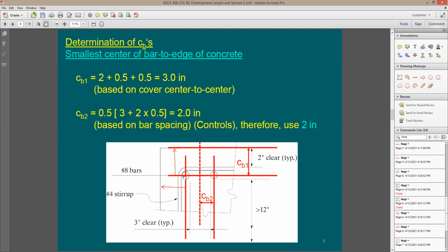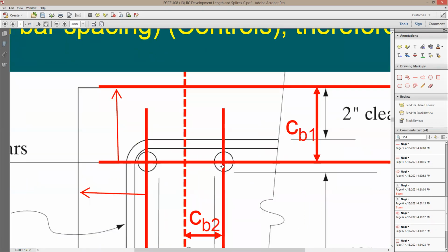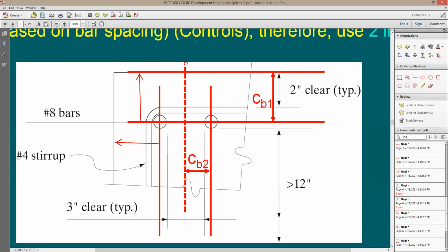So this works fine. I mean, it is easy to explain it when it comes to a corner rebar here. But the question is, how about this rebar? Where's the edge distance? I'm going to say I have here 2 edge distances. This one is a clear one that you can just look at and figure it out yourself. The other one is going to be based on having an imaginary surface or edge of the concrete, a free surface, which happens right between these 2 rebars.